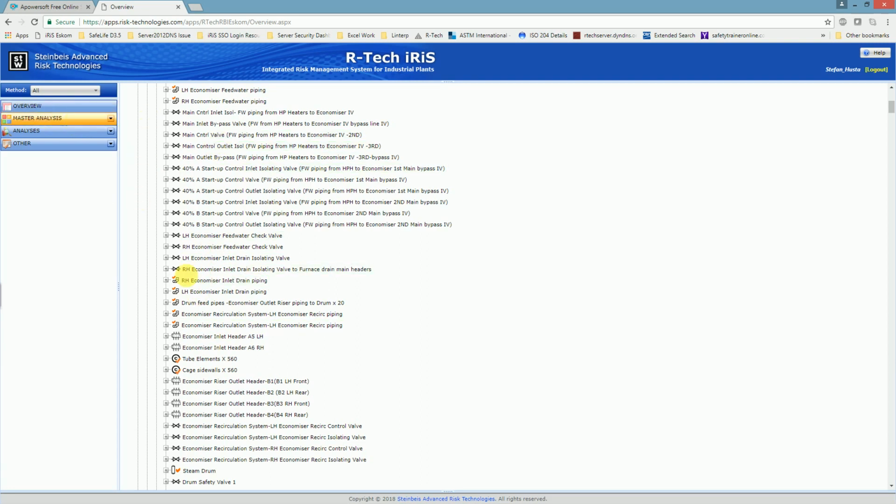To avoid going back to the master, if I was to go there and in the master select any station, any area, go inside and change the show as component name to functional location code, what would actually be shown here in the list in this instance would be the functional location code. So you would have NA10G001A5 here shown in the tree, and NA20G001, and so on. And hovering over those functional location codes of the different components, you would get the other two names.